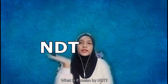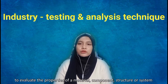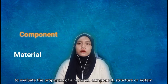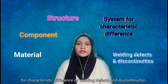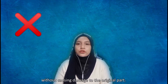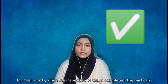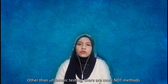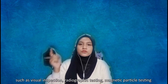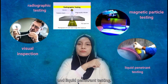So, what does NDT mean? NDT is a testing and analysis technique used by industry to evaluate the property of a material, component, structure, or system for characteristic differences or welding defects and discontinuities without causing damage to the original part. In other words, when the inspection or test is completed, the part can still be used. This is one of the major advantages of NDT methods. Other than ultrasonic testing, there are more NDT methods such as visual inspection, radiographic testing, magnetic particle testing, and liquid penetrant testing.